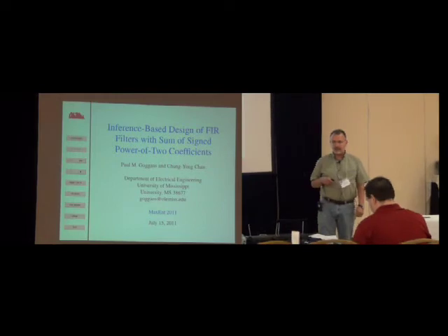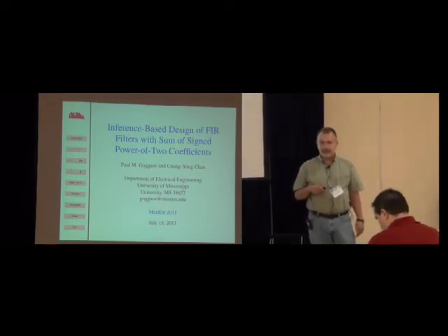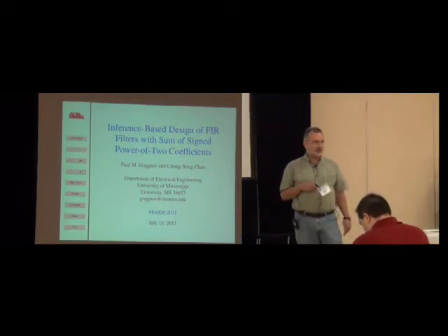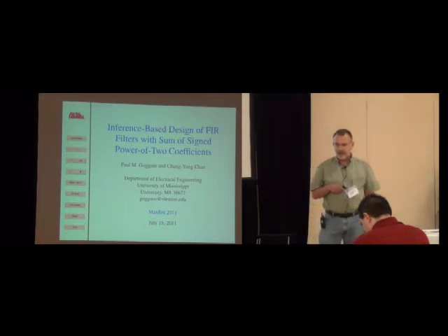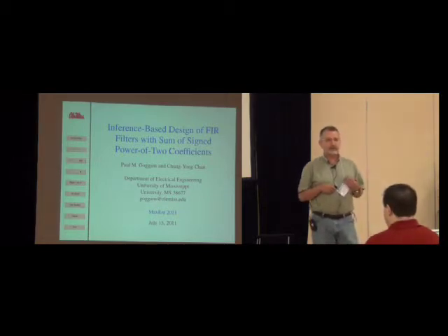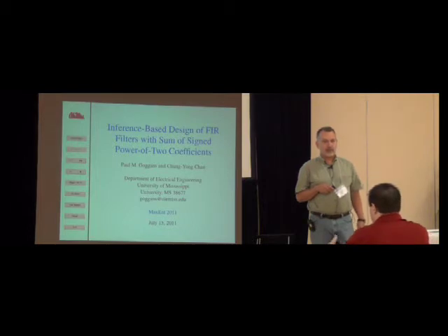Today I'm going to talk about the inference-based design of finite impulse response filters of a particular sort, filters that have coefficients that are made up of the sum of assigned power of two coefficients. The significance of this is that digital filters are often used in real-time systems.